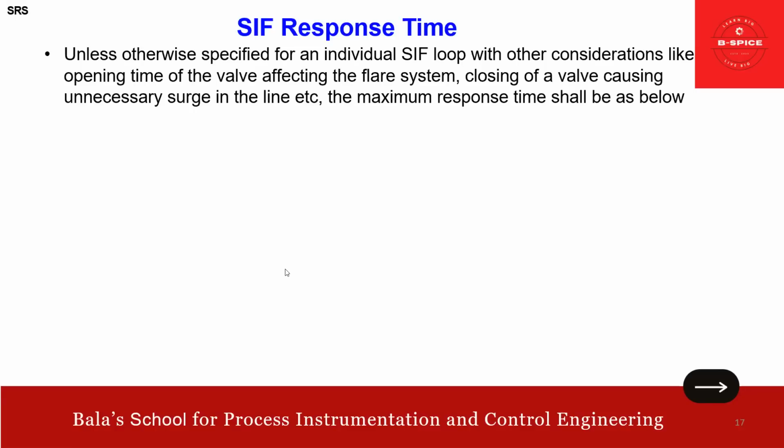Okay. Then a few more. Unless otherwise specified for an individual SIF loop with other considerations, like opening time of the valve affecting the flare system or closing of the valve causing unnecessary surge in the line, the maximum response time shall be as below. You got it, friends?